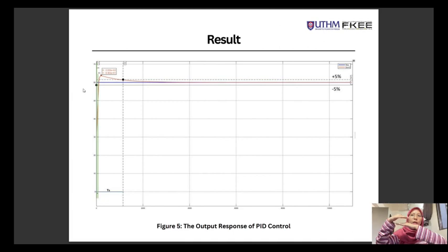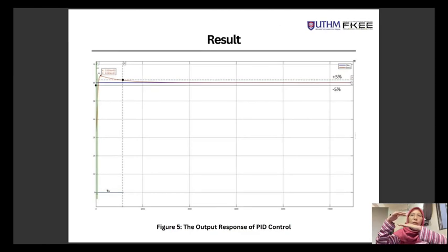So when the signal is finished at the settling time and enters like this, it has the band there. And also at here we have the 90% and 10% for the rise time, and this is actually TS.